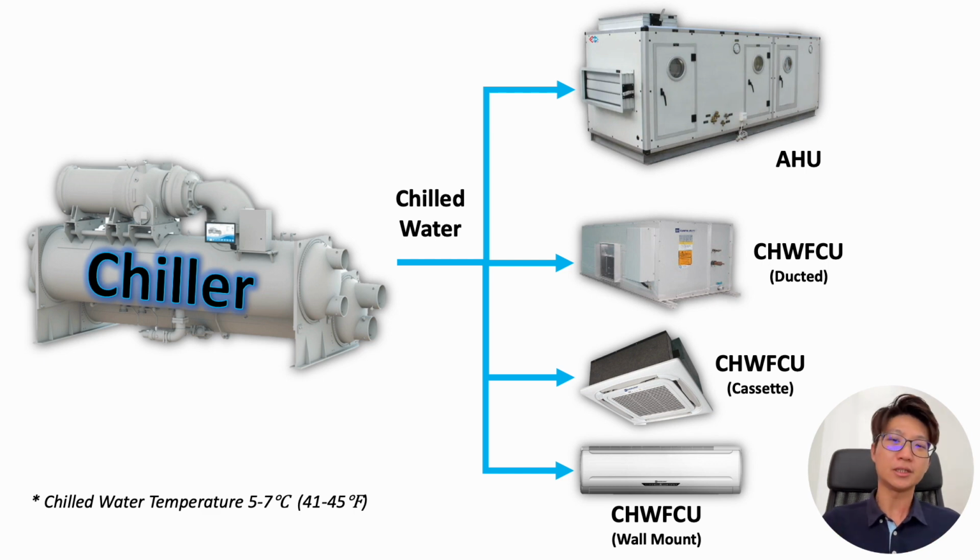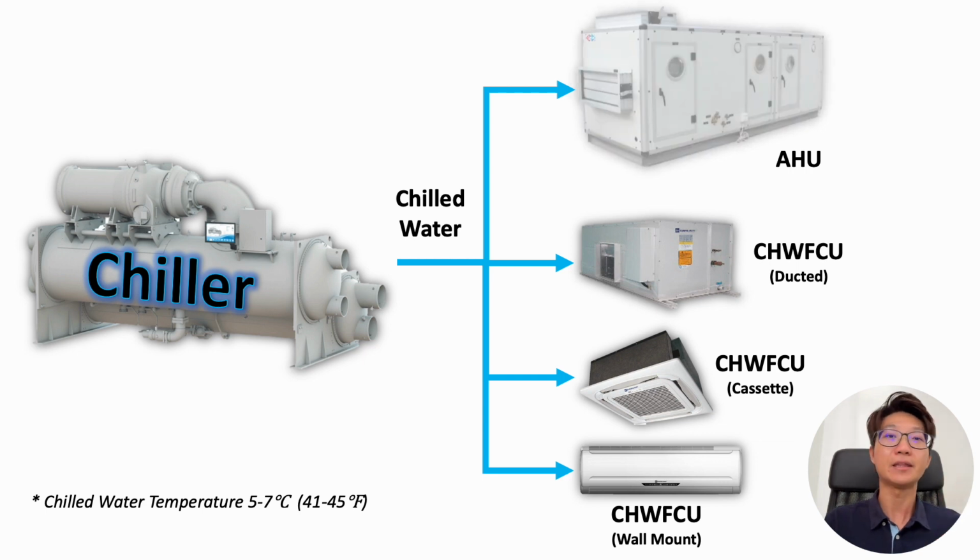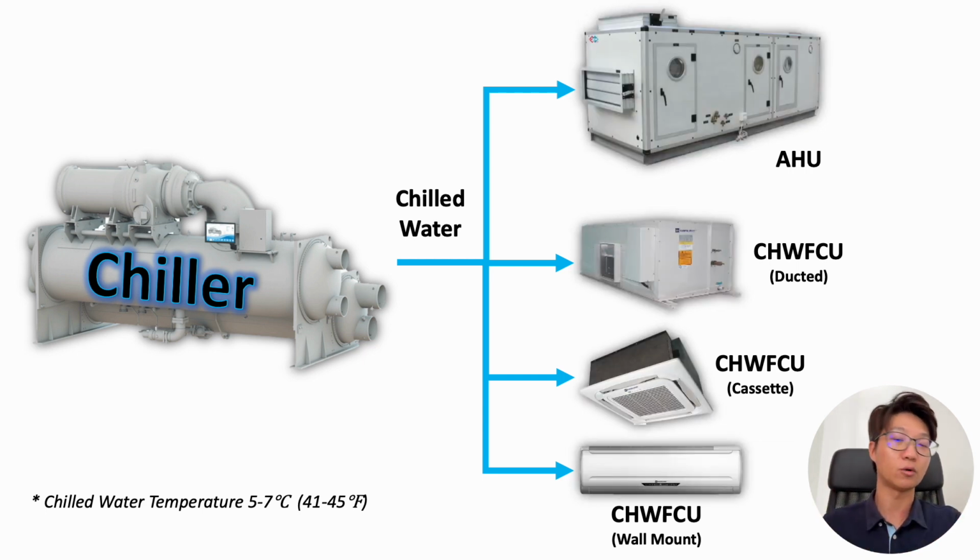So a chiller, right? What is a chiller? What is different between a chiller and our house air conditioner? You see, a house air conditioner uses air to cool things. A chiller is different. A chiller will produce cold water. Then the cold water will be sent to those air conditioners that we call air handling units and fan coil units. Then they will produce the cold air.